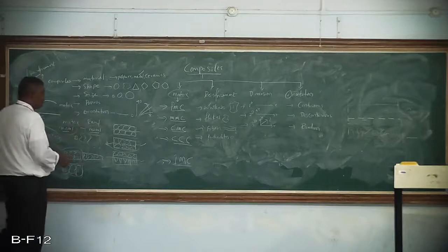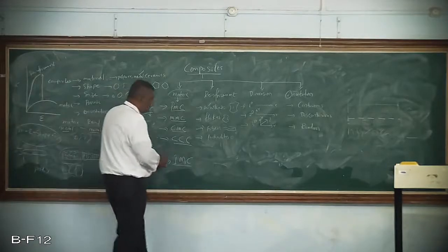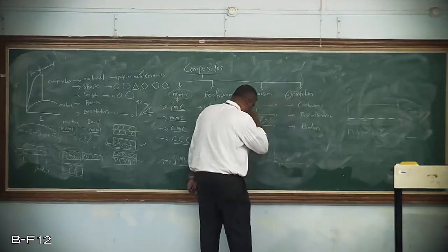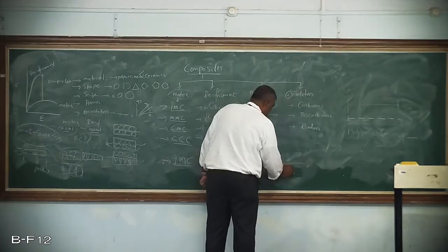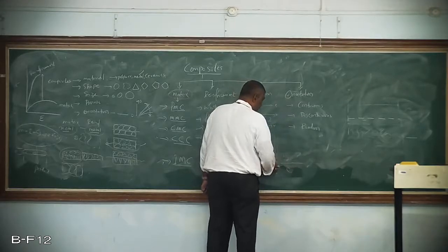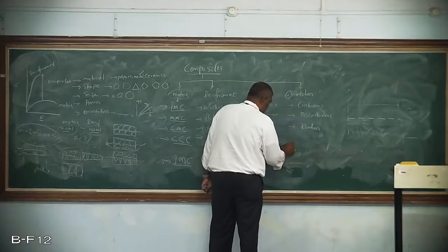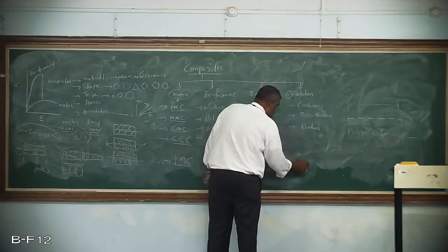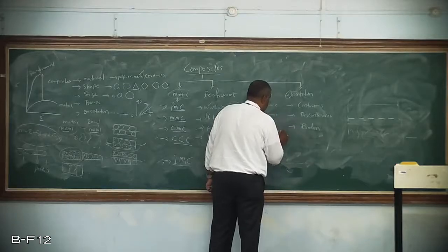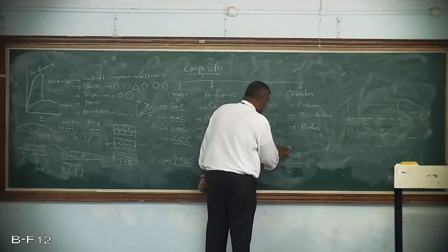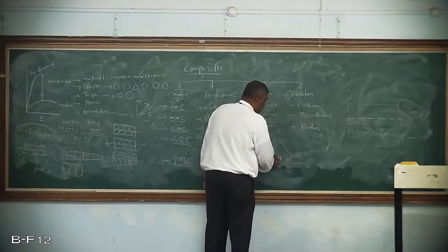Next is orientation. With stress and strain, if the fibers are oriented in a particular direction, then this is 0 degrees, this is 90 degrees. The strength keeps decreasing.